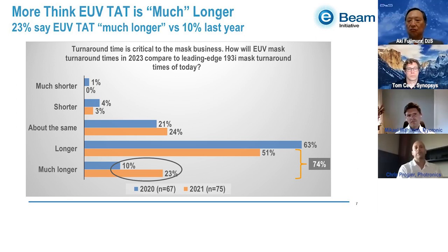People do not want to scrap masks. So the repair loop is taking a lot longer than it used to as well because the validation and feedback is weak. EUV aims, all that stuff. So these numbers, I think, are real, and they are a surprise and a problem. Eventually it will become an impediment for EUV adoption. So I think they have to be worked out, this turnaround time for EUV masks.